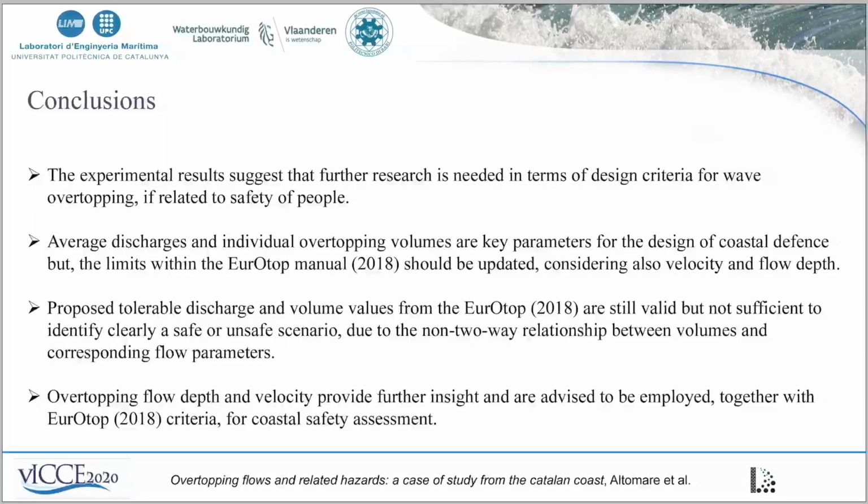We can also say that average discharge and individual overtopping volumes are still key parameters for the design of coastal defense, but our work proves that the limit within the EurOtop manual should be at least updated, considering explicitly the velocity and the flow depth that are actually associated to the individual maximum overtopping volume. So the proposed tolerable discharge and volume values from EurOtop are still valid, but are not sufficient to identify clearly a safe or unsafe scenario.